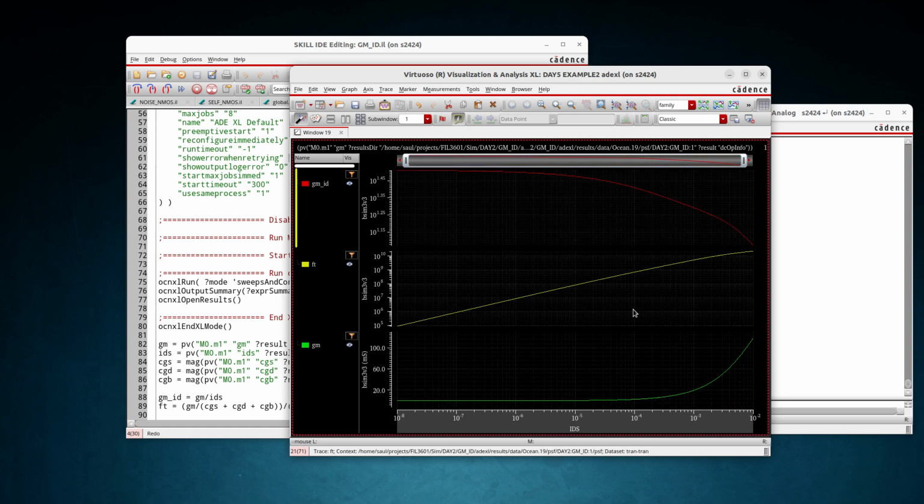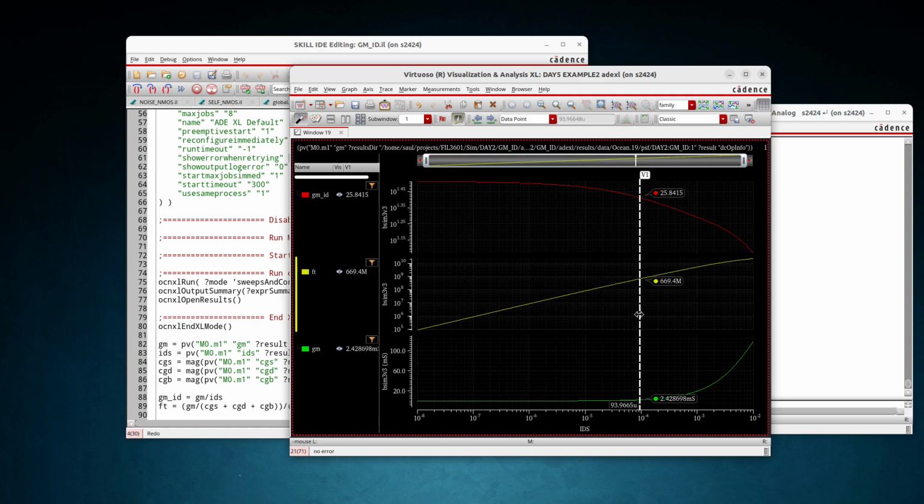We split it, and then let's see, we need around 6 or 7 millisiemens, and for this transistor, let's say for 400 microamps, I get almost 9 millisiemens, FT of 2.4 gigahertz, which might be perfectly enough in this application, and much better.